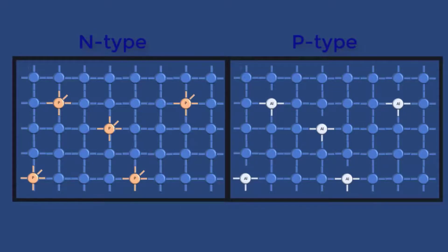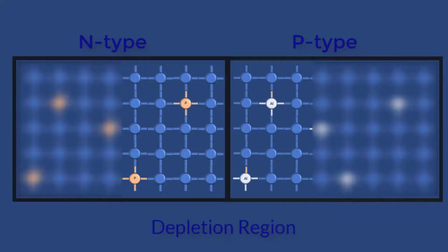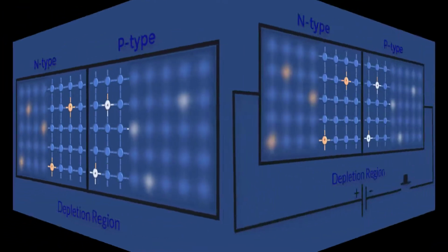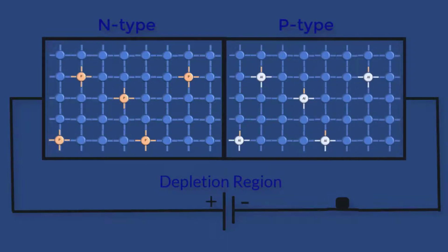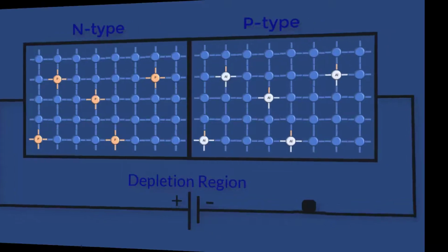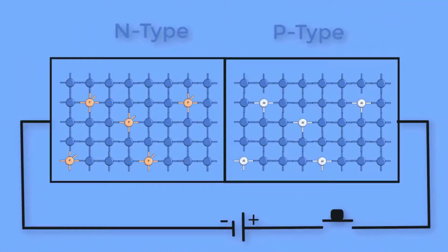The p-n junction allows holes and electrons to combine in a very narrow region around the join, called the depletion region. Reverse biasing causes the depletion region to become wider, so no further recombination of holes and electrons can happen and no further current can flow. Forward biasing the device greatly assists the hole electron recombination process and current flows easily.